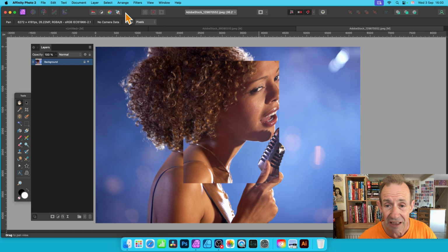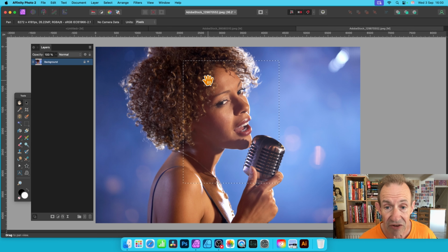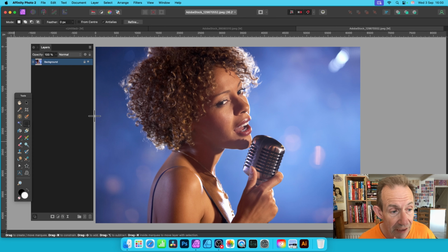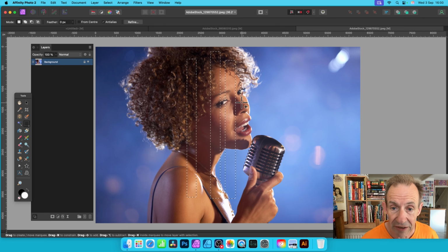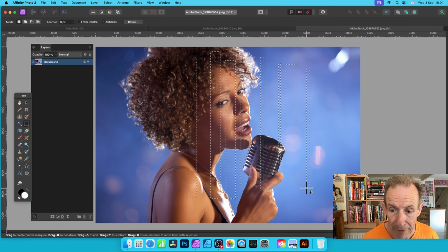But the selection box you can see here, you can change it. You can apply, of course, more than just a basic rectangle. So let's just undo. I can go over here, and with this rectangular, I could hold down the shift, equivalent of going up here using the add option. So hold the shift, you can see now the cursor changes, and now you can add to this selection. And you can make thin lines. Let's just create very thin lines like this, like that. And you can, of course, add them any place like that.